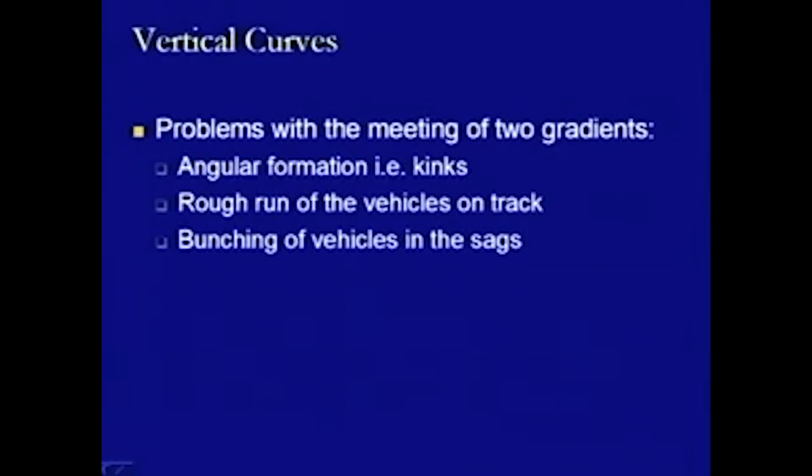connectivity through which they have been jointed together, they can be pushed inside, and when there is a bunching of the vehicles, then those connectivities will remain inside of the wagon itself, and there will be very little distance left between the two bogies. So, this is another effect of the sag or of the gradients which have been provided, and this may also have its safety implication in the sense that as we are moving towards the sag, all the vehicles or wagons will be trying to hit each other.